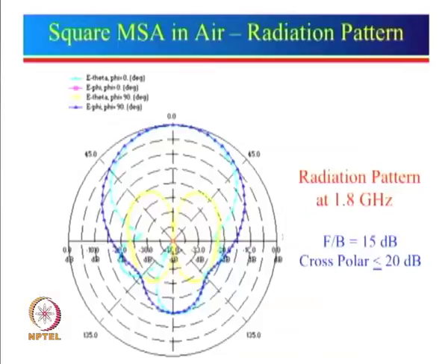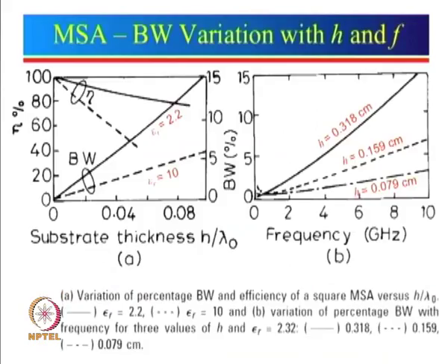The reason is that when we looked at this curve here, we actually noticed that one can get an absolute maximum of 15% bandwidth for a given simple patch. In fact, most of the time only 5 to 10% is achievable. Now suppose we require a bandwidth of 20%, 30% or more. So the technique is to use multiple patches so that they excite close to each other.